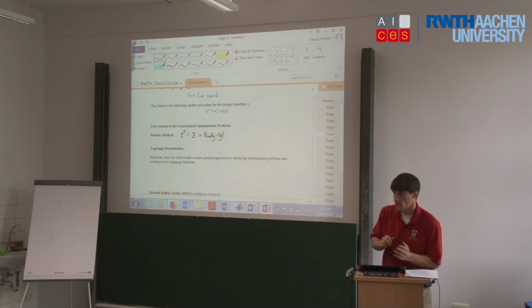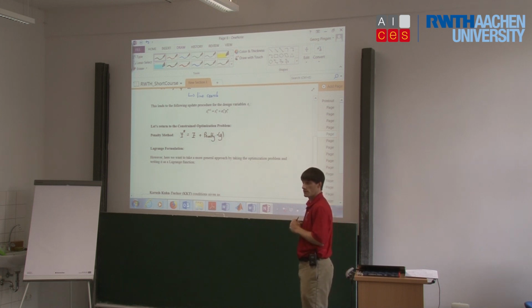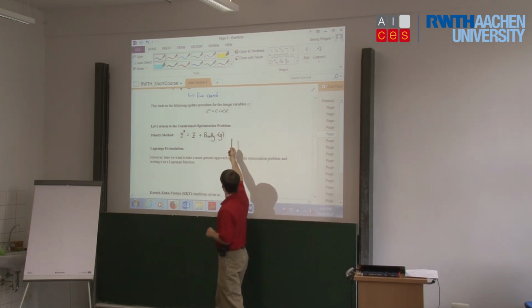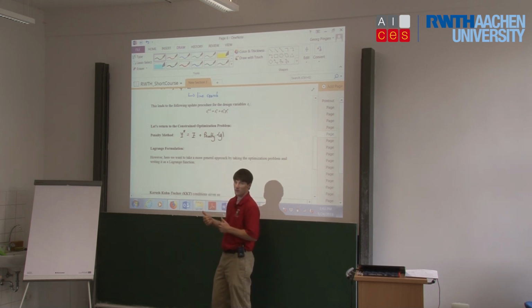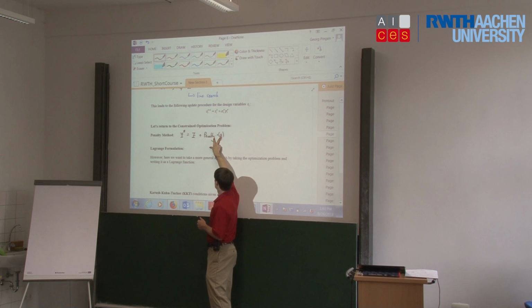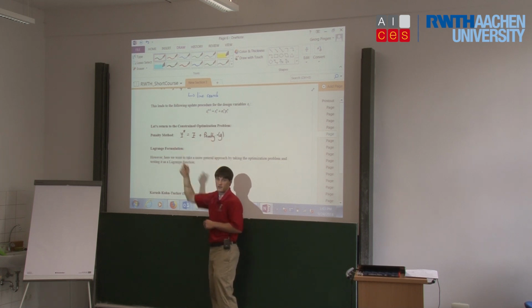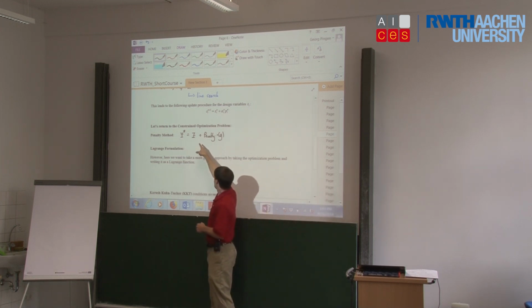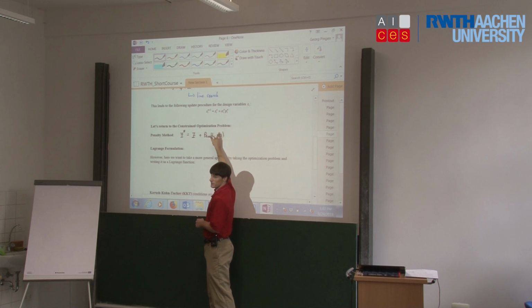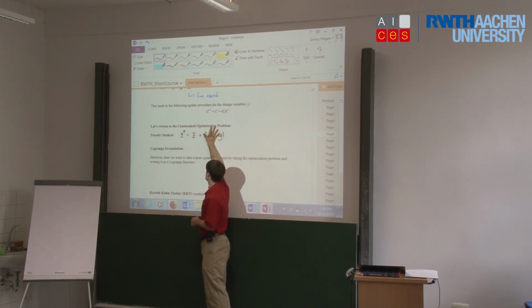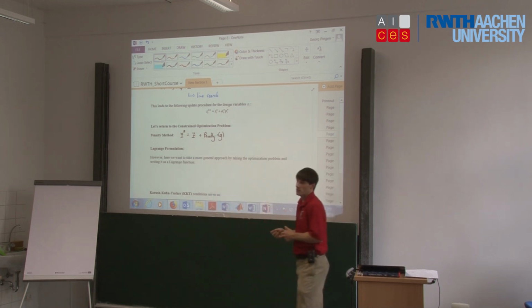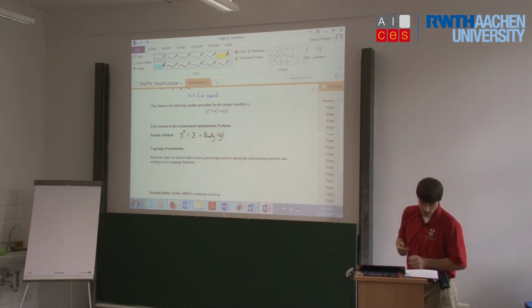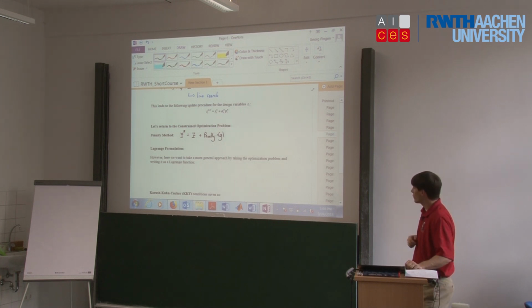Okay. So we have a constraint g, which is maybe the volume, and if the constraint is satisfied, this product will be 0, but if the constraint is violated, we take this violated constraint, we multiply it by a penalty and add it to the objective. So if we're trying to minimize z, we'll want to get rid of this penalty. If this is satisfied, that will eliminate this term, and then we can minimize z. And so that would be a penalty approach. We'll talk about this a little bit in a minute, but we're not going to focus on that.